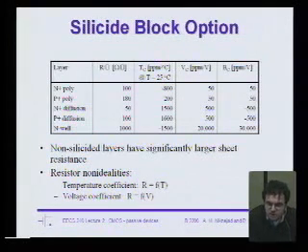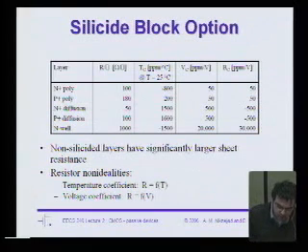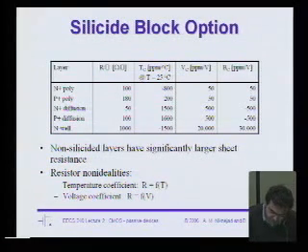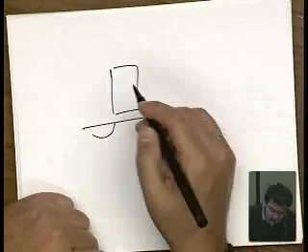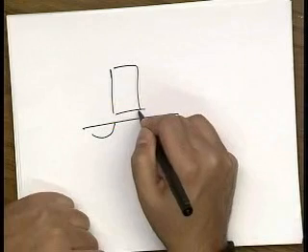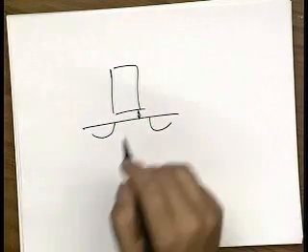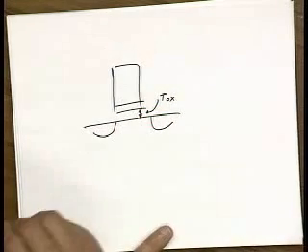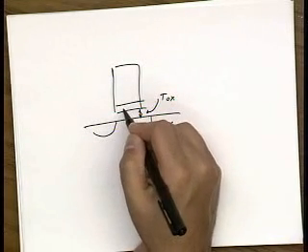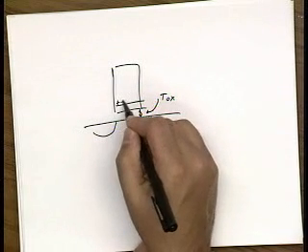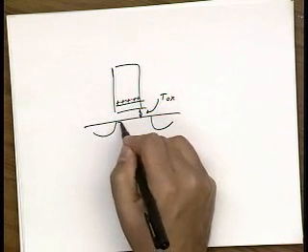Yeah, poly depletion. So even though our polysilicon resistors are not physically touching the substrate, so they don't necessarily get reverse bias like a PN junction, they still will get depleted. So in a transistor, I'll draw a real quick cross section. If you build a transistor like this, you find that the actual oxide thickness, if you measure the CV curve, is not Tox, but a little bit higher. And that's because the carriers are actually depleted and don't flow all the way to the edge here.